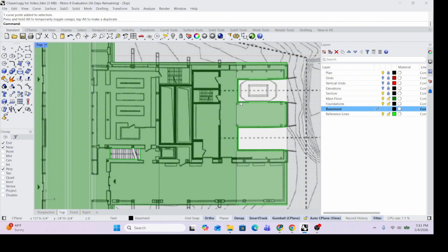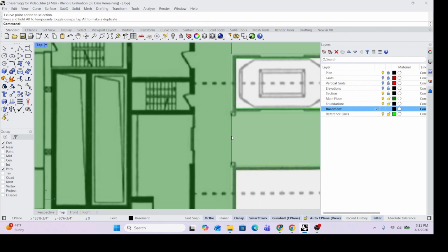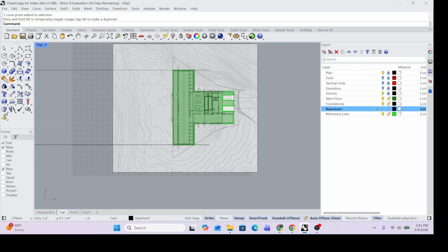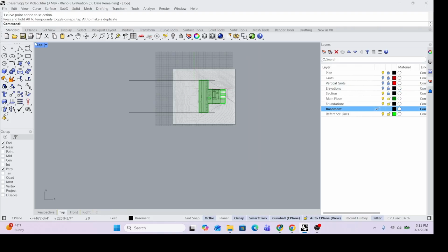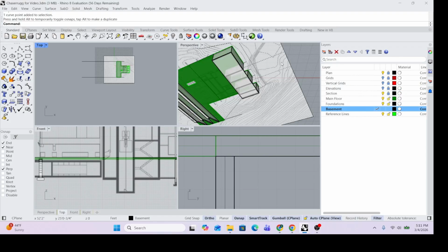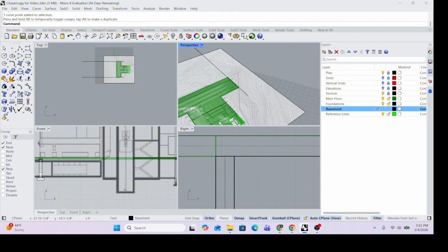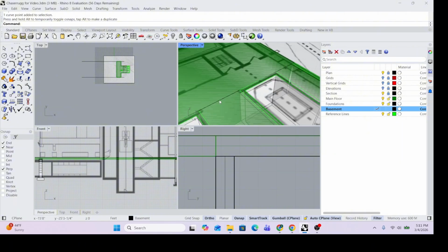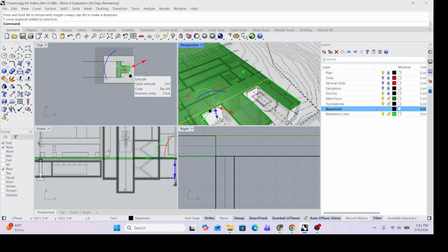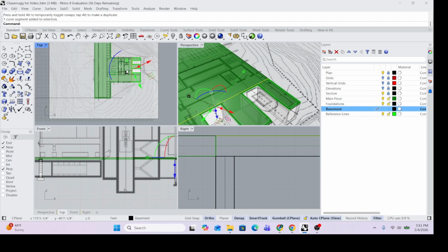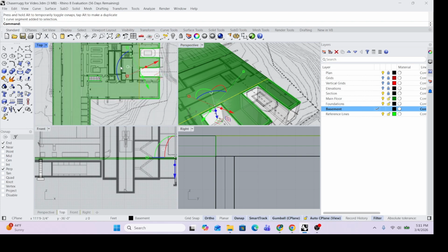We know we have a 1 foot thick wall here and we've got some overlap. If I hold Control Shift and I make sure I'm not on that wall, but I'm just on the line, which will be a whole lot easier to do from here. So I'm going to hold Control Shift, click this, and now, that's a bummer since I did it from this view. I'm going to double click this to reorient it.